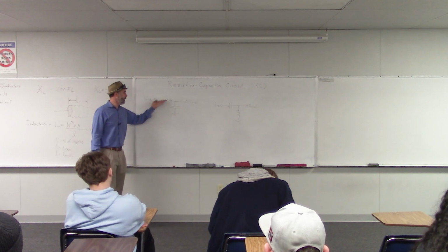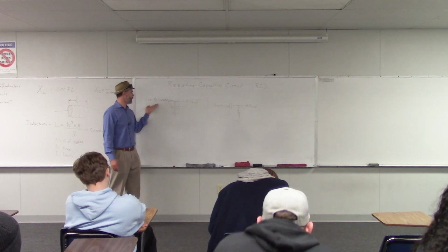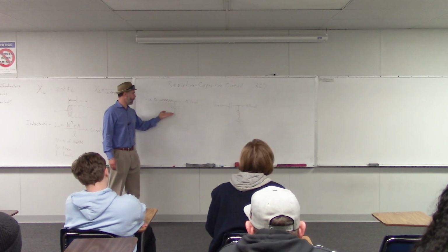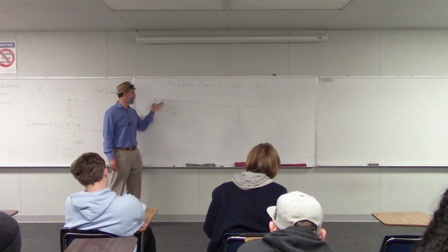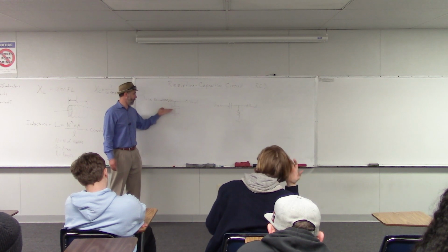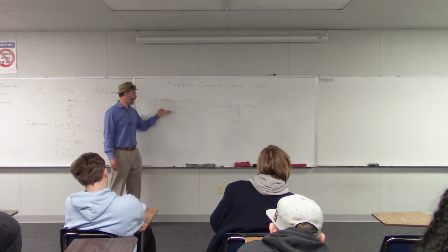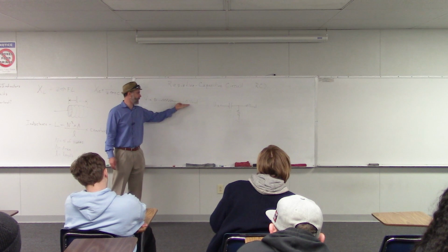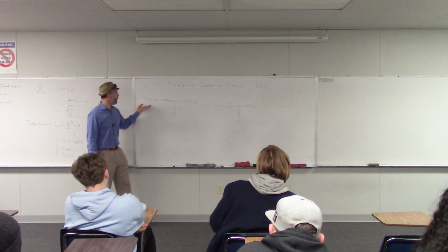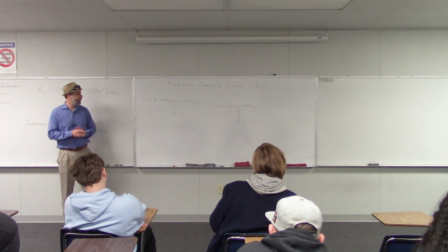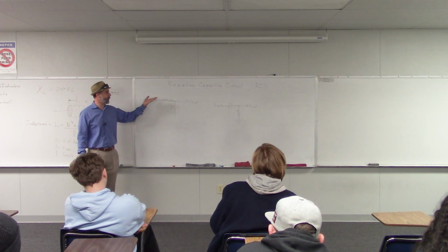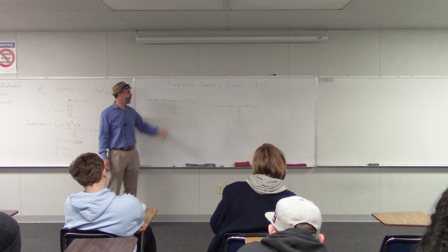Whereas over here, the capacitor is going to ground. So high frequencies have a path to ground, and they don't get through, whereas low frequencies can't go to ground. They're blocked from ground. So low frequencies pass through to the output. So we call this filter a low-pass filter. Okay? So electronic filters are another application for RC circuits.